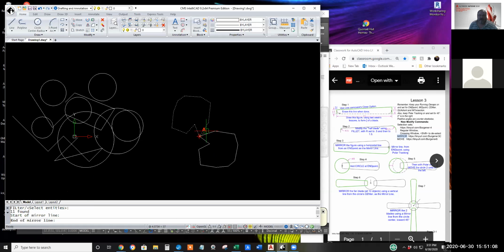Just like AutoCAD, I can O-snap on the midpoint of the line, or let's click on the head of the insect. Click. Just like AutoCAD, it says, hey, do you want to delete the original entities? AutoCAD said delete the source objects instead of original entity. Just like AutoCAD, it's guessing you're going to say no. So just hit enter, and it'll accept the default no, and there's your butterfly or moth.